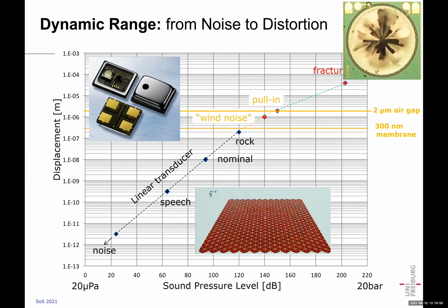Yeah, and beyond this, of course, from a lot of studies on a very special microphone, you find a fracture limit where the diaphragm is blown off at several bars or tens of bars. For very short times, like milliseconds, they can hold, but of course it is close to the situation of burst of the membrane. Then the device will fail. So of course this failure we will discuss later on in discussion on fabrication, packaging and testing and so on.